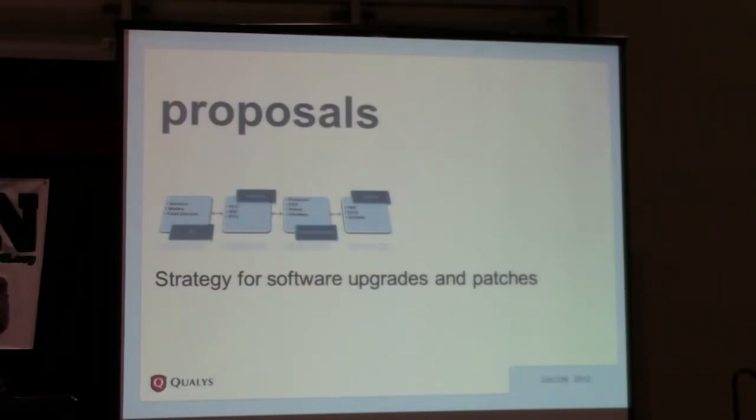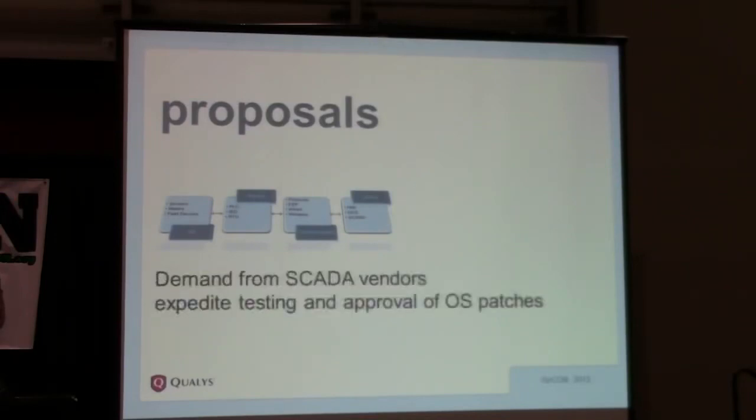I know it's very expensive, but try to have a sort of mini system of your big SCADA system where you can apply patches and test those patches. Having this test environment will go a long way, even though it may cost you a considerable amount of money.